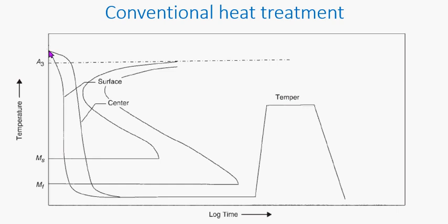So just as in annealing, but in this case, instead of cooling under normal atmospheric condition, it will be cooled fast. We call it rapid cooling or quenching. As we cool down here, it crosses this S curve, which is specific for each alloy.